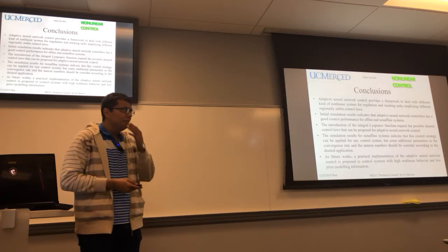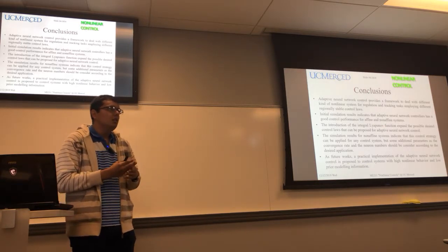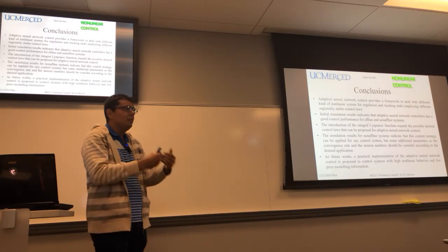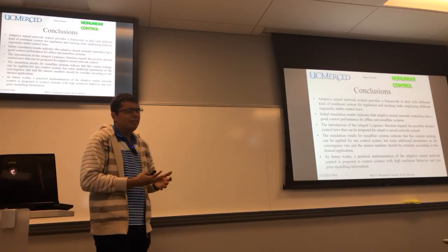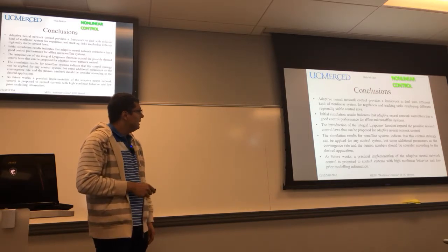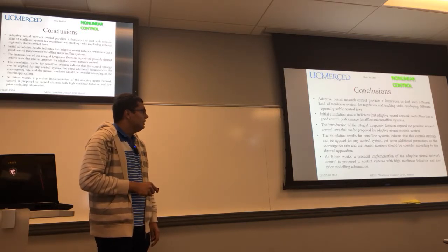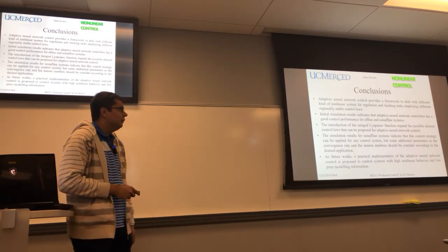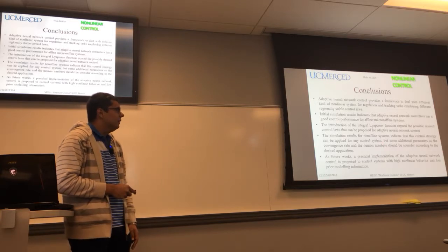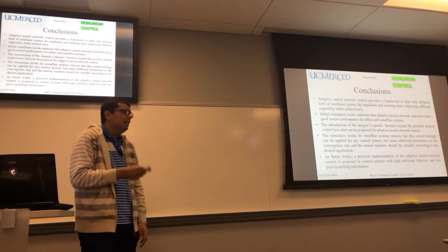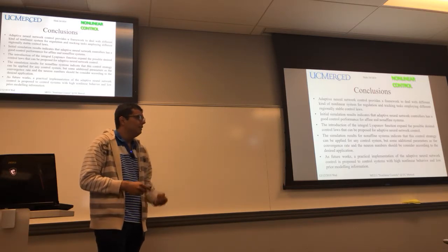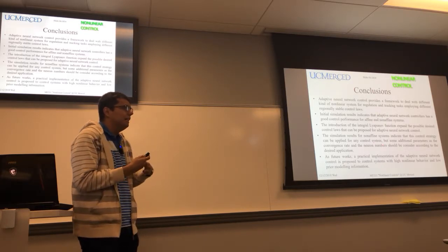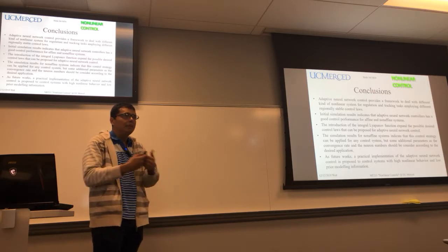The integral Lyapunov function gave us the possibility of not only eliminating all the nonlinearities, but dealing with the nonlinearities that work for me, or can help me to improve the system. The simulation results of non-affine systems show that this neural network approximation works, and we can employ this for any kind of systems. Considering the word non-affine, we can say that most of the nonlinear systems are non-affine if we go deeper into their modeling.